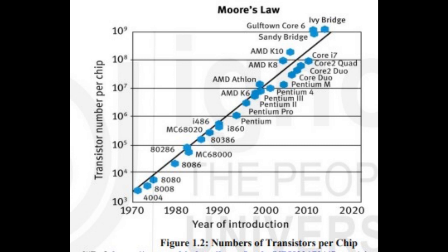The integration growth can be more easily understood in terms of feature size. Feature size is that dimension of the transistor that is required to be minimized without changing the functionality of the device. So, a decrease in feature size will eventually increase the number of transistors per chip, which in turn will result in the development of new advanced chips having advanced functionality. This has resulted in growth of semiconductor memories, RAM memories, so that now designers can trade off speed with memory size. Figure 1.2, number of transistors per chip.